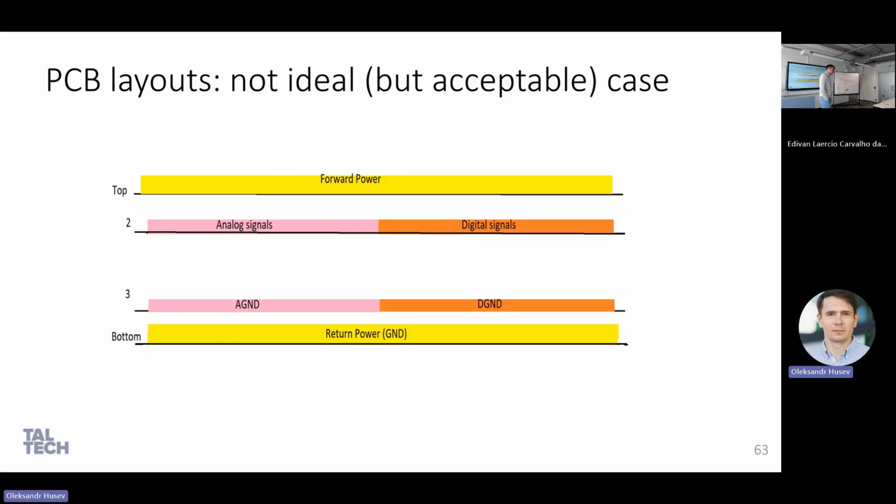So the art of PCB design is to solve the tasks that you have, like proper operation and probably some EMC requirements, but at lower cost. Then it is unavoidable. I never met such cases, honestly, in my experience, where it's unavoidable and I must pay for this. In most cases, I never met such a case. Increase your PCB size, for example, if you don't have space. It will be much cheaper.